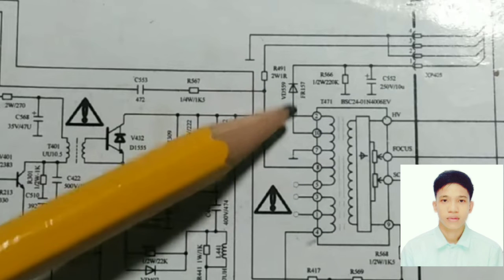And now there is some issue when the 180 goes up. In that case, your output of the flyback is not normal, because the voltage exceeds above 180. In that way, it is possible to break the horizontal transistor, or it may be the flyback.